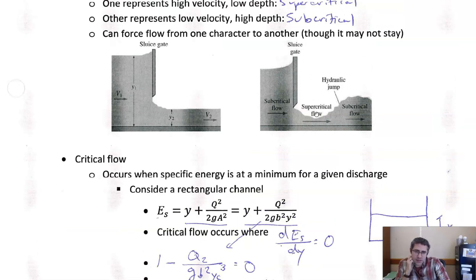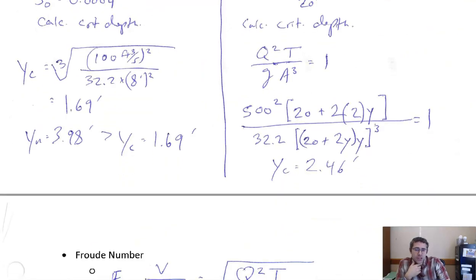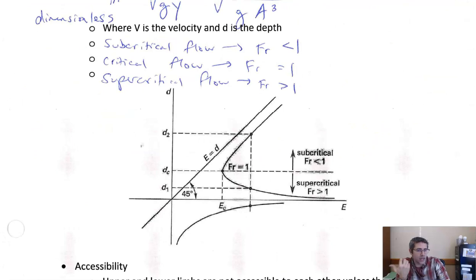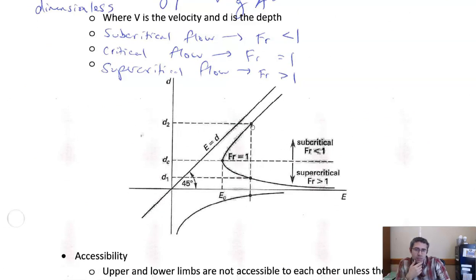Here I'm definitely not in uniform flow. I have a depth here, I have a depth here, I have a depth here, it's changing. So as my depth changes, we'll talk later about hydraulic jumps and kind of show that they actually do lose energy, but maybe this one's more helpful. My depth is going from high to low. I might not be actually losing any energy overall, but I'd be going from depth high to depth low, and I have to stay on this curve.